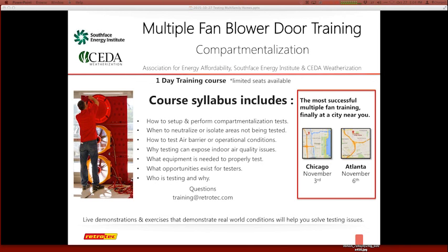And one of the key inputs is the number of square feet of opening you have from your test floor to the rest of the building. The other key input would be the maximum amount of stack that you would expect on the day of the test. Armed with those pieces of information, we can tell you where the fans need to be located in the building. In this case, we had to open up one of the elevator shafts to get air to the upper floors, and when we did so, we had the same pressure in the building within a few percent.